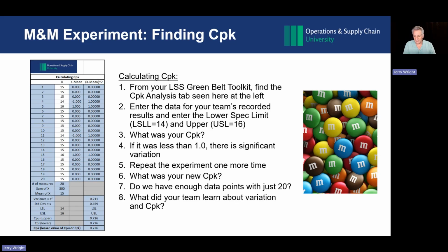And by the way, the CPK sheet is just a calculation in Excel. There's nothing complicated to it. You'll have that from your toolkit, and you'll be able to do CPK on any data attribute you'd like to measure, see if your process is capable.